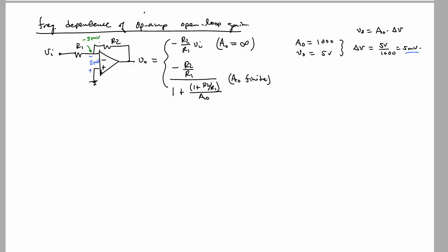So what I want to do, just as kind of an aside, but I think it'll be useful here, is resolve this problem with a slightly different approach. We can actually use an ideal op amp. Okay, so I put I for ideal, in other words, infinite gain. If we connect a source here at the non-inverting input, and we give it a value of minus 5 millivolts.